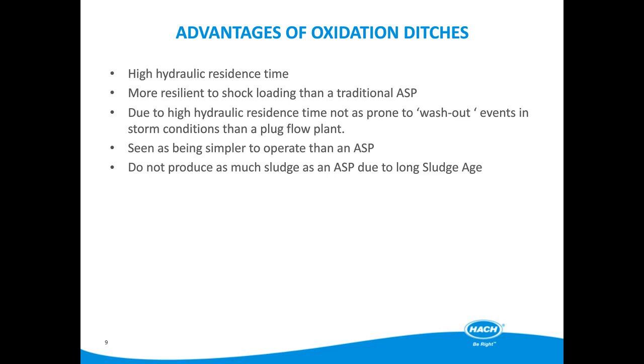However, if denitrification is required, redox or ORP measurement can also be used to indicate the change from the oxidizing conditions where ammonium is converted to nitrate and the condition when nitrate is reduced to elemental nitrogen. The typical redox values are as follows. For the oxidation of ammonium, this occurs in the ORP range of plus 50 to plus 325 millivolts, and the reduction of nitrate to nitrogen takes place at redox potentials between plus 50 and minus 50 millivolts.